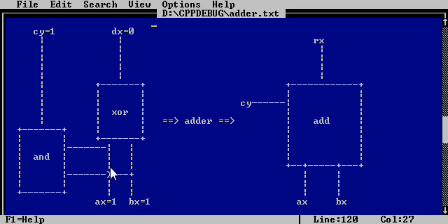What I'm trying to do is put two inputs in and have the addition occur. Remember I showed you that XOR essentially does the addition part as normal. And what I want to happen is that when these are both 1, I would like an extra output to be 1, called a carry. Now you're starting to see what all this carry stuff is about. So let's see. Clearly the first part's going to work. Let's fill that in there.